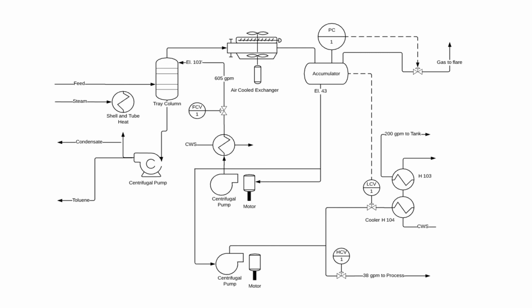So ways to go about reading them is following the method I talked about if you're looking at a specific line, or just looking for the piece of equipment, so maybe the tray column, and then looking at all the inputs and outputs around the tray column or whatever piece of equipment.